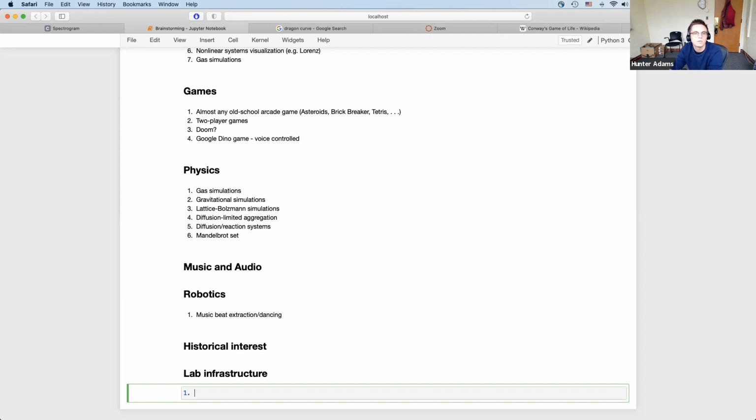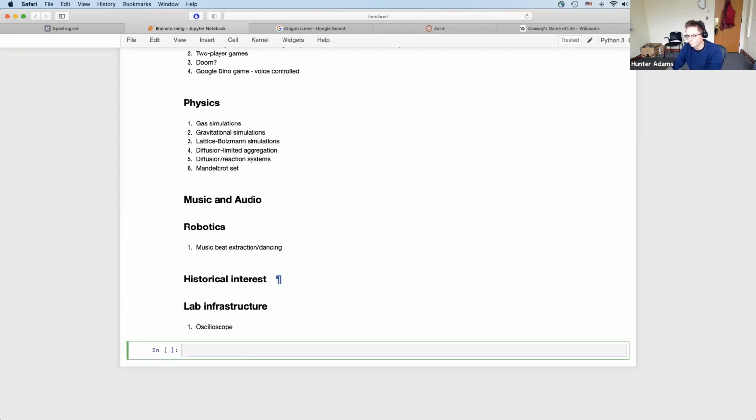That samples the ADC at some rate and then shows the waveforms on the TFT display and allows the user to do things like set range in both the X and Y directions, both the voltage and the time dimensions, set the trigger value, set the trigger settings, that kind of stuff. So you could make a small PIC32 oscilloscope. Might be kind of fun for people that are interested in infrastructure sorts of projects.